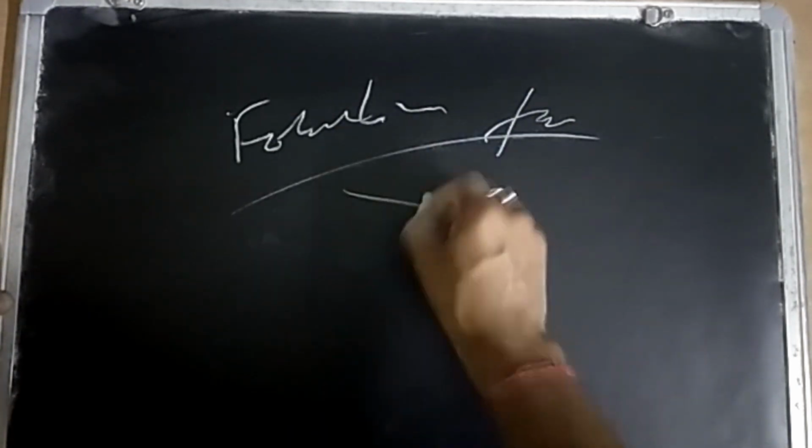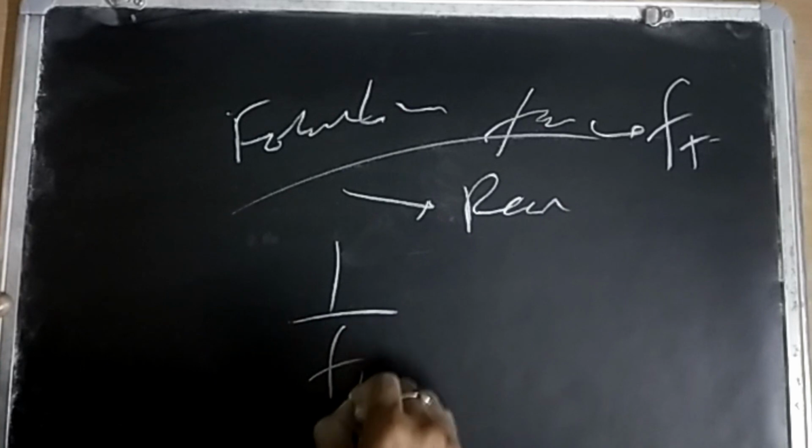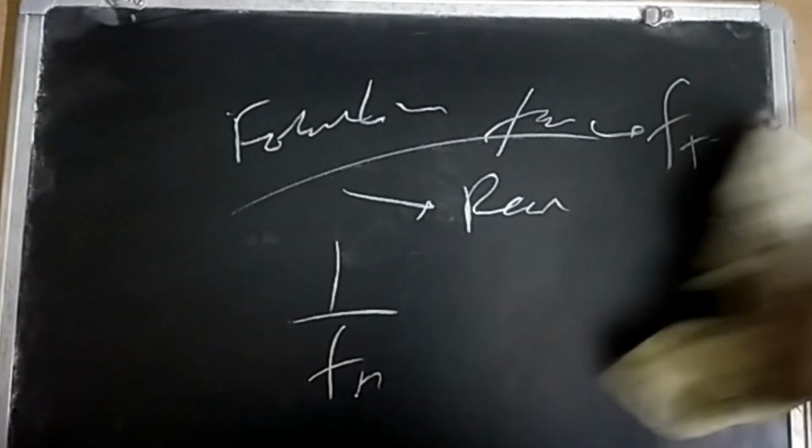And fouling factor, okay, I'm not writing it like that, but fouling factor is just the resistance. Let's say the factor is given F, then this is 1 upon F. This is the resistance, because the fouling factor, this whole thing, is actually the resistance that is given. Next, you can check the units of that factor that will be given in the question.